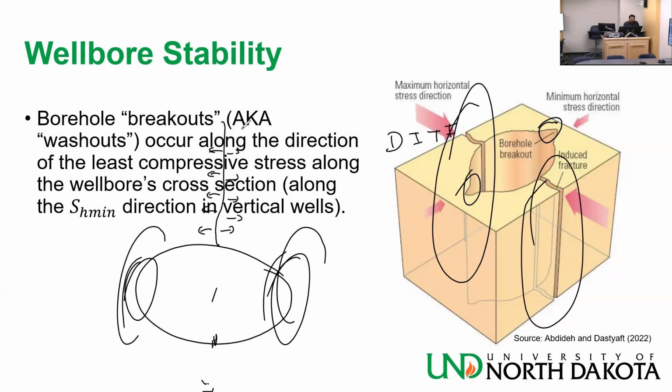This fracture is, essentially speaking, a hydraulic fracture, or geologically speaking, an artificial dike, which is basically the same thing as a magmatic intrusion. It's a tensile fracture, whereas borehole breakouts are shear. This stuff here is shear. This is tensile. Drilling induced tensile fracture.